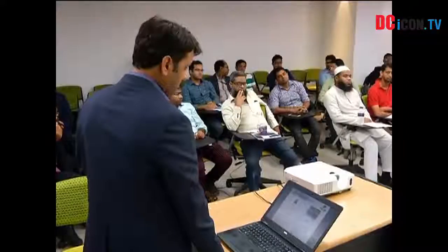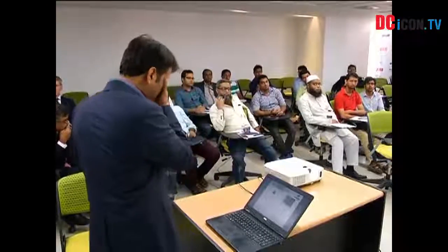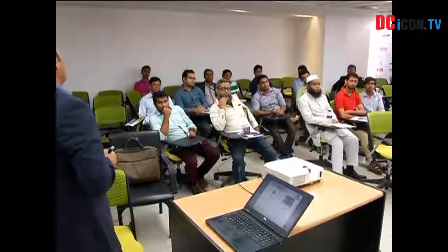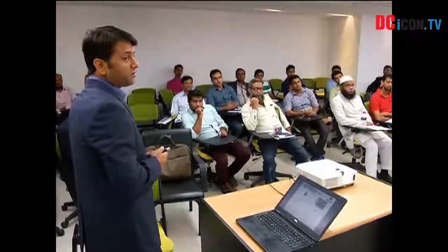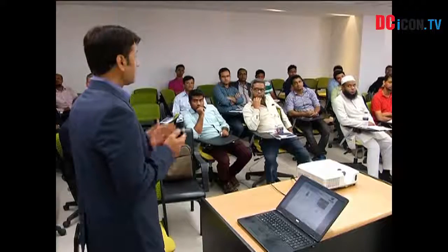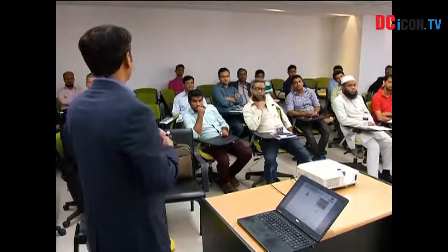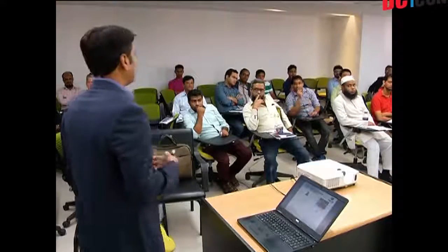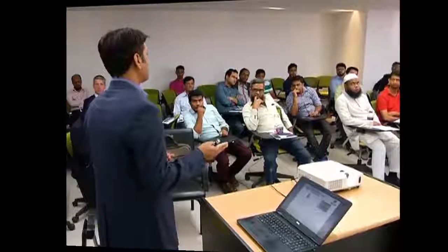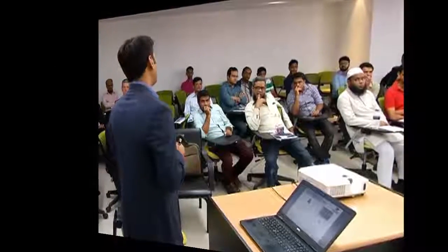It's proven. Static UPS, that is IGBT and SCR. So UPS harmonics. Does a rotary UPS need any filters for harmonics? That's a good question. I have not focused on specification comparison. We focus more on the concept that you should look at flywheels as an energy storage, reduce your air conditioning, but the specifications of a rotary UPS in terms of harmonics are better for both output and input without any filters.